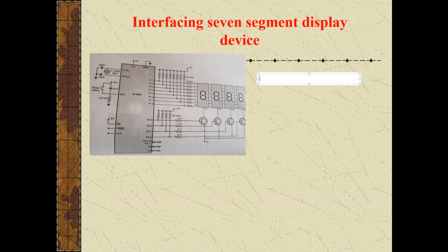So we have to write the starting program. We write the code MOV R0, #8H. We are writing a program for the 8-digit LED display, so we have to initialize the counter for 8 digits. There are 8 digits we are going to display through the 7-segment display. So we initialize our counter using register R0 with the value #08H.